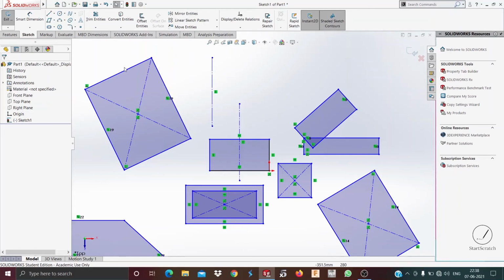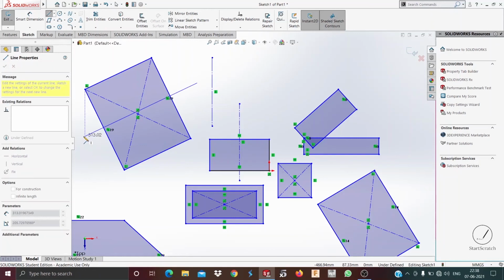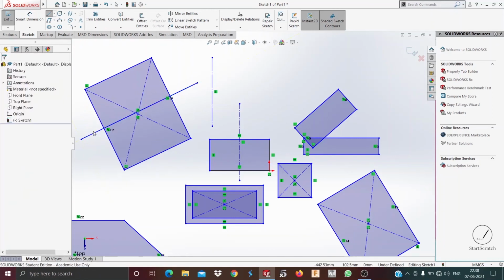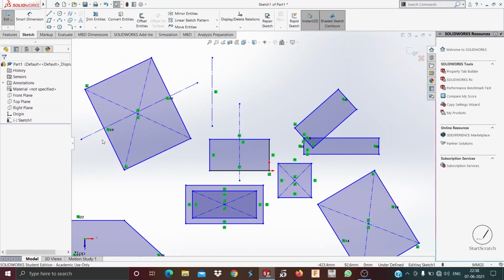Like when you extrude this rectangle, I'll draw a construction line. If I draw this here, like I want to draw some construction line for some purpose, I'll draw this, okay, and I'll change this line to a center line. Sorry, construction line. Sorry about that. So now when you extrude this rectangle, the only lines which will be considered are these 4 lines and not this line. This is basically just, as the name suggests, for construction only.